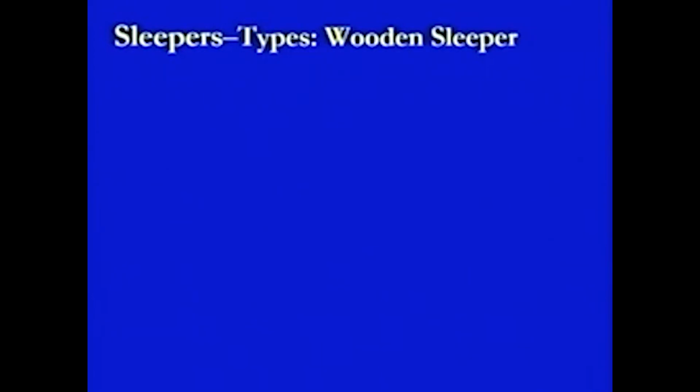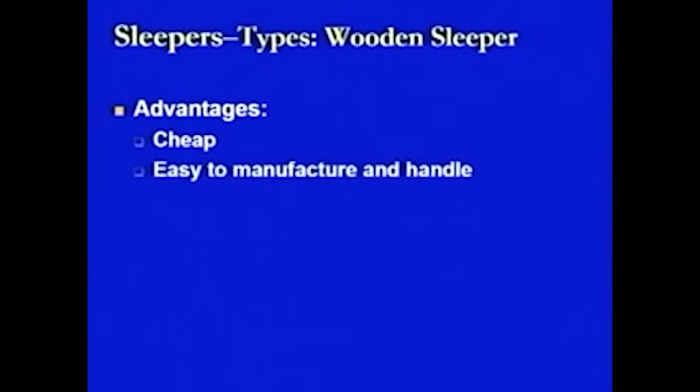Now, we are starting with the different types of the sleepers. We will be starting with the older version of the sleepers, that is the wooden sleeper. There are certain advantages of using a wooden sleeper. One thing is that they have been cheap in the older days, where there was a lot of wood available around, but nowadays we do not say that it is as cheap as it was relatively in the older years. They are easy to manufacture and they are easy to handle.